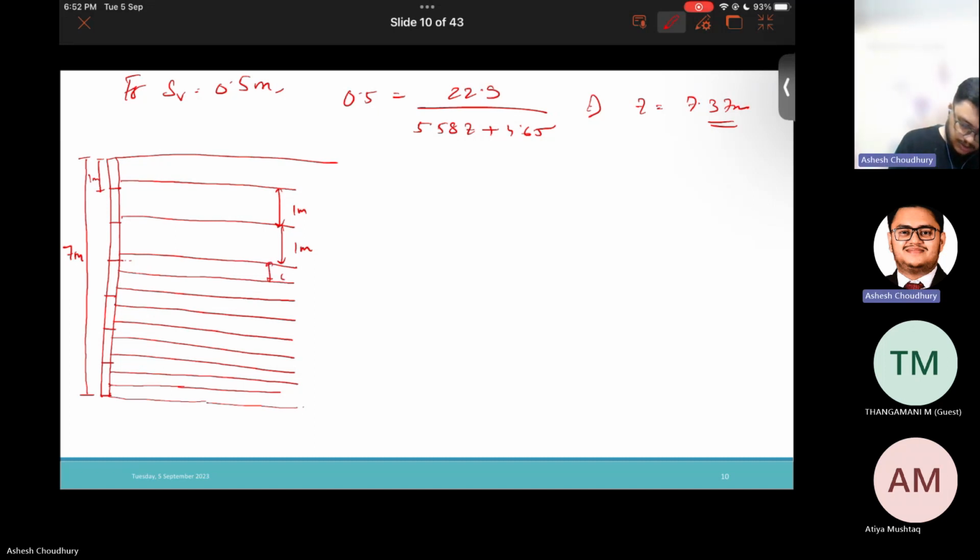After that, we have ellipses with 0.5 meter. So if we count the total, 11, 10, 1. All right. So these are the 11 geogrid layers that we can place. The top 3 can be 1 meter spaced, and for the bottom we are providing 0.5 meter spacing.